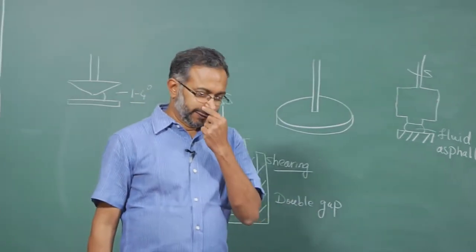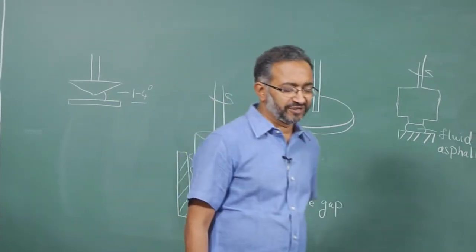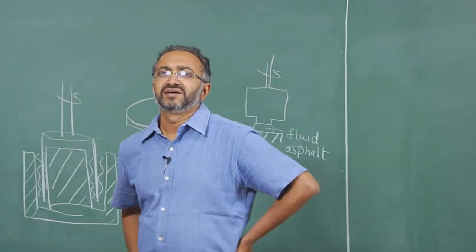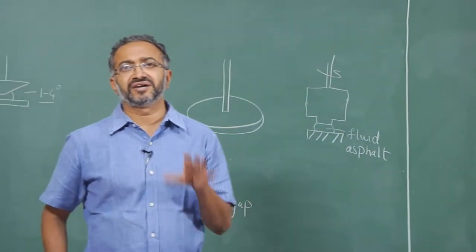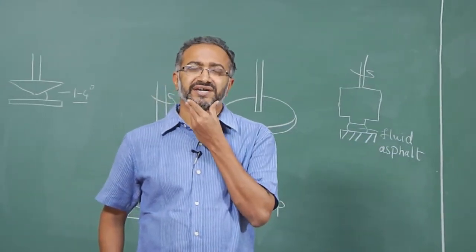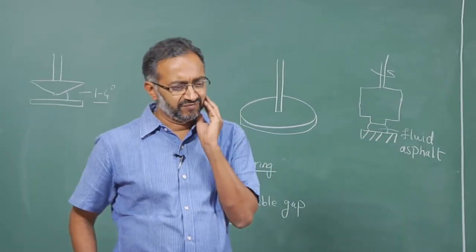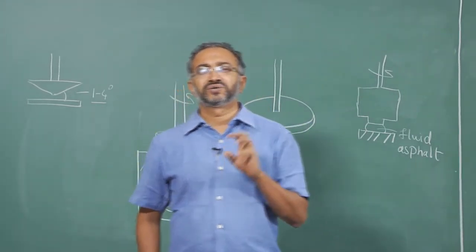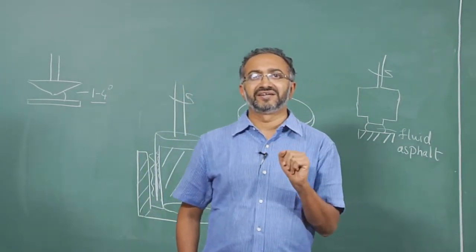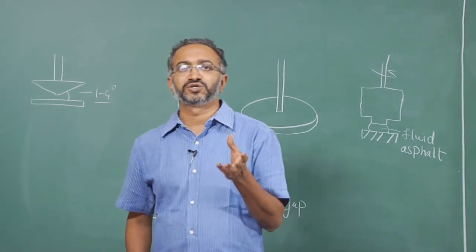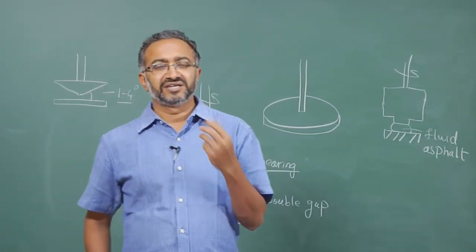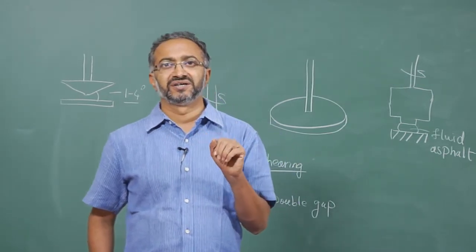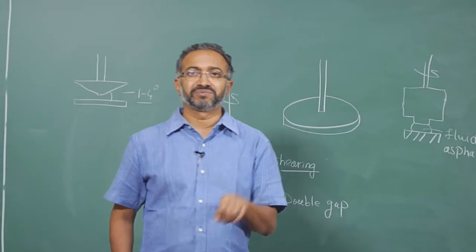So one useful thing in any instrument is to have some standards. Whenever we are trying to measure something, in case of rheology, silicone oils are used as standards. These are available from various vendors, and these are fluids of standard viscosity. So we know what the response of this material is, and to check the working of our instrument, to check the conditions under which we are measuring, it's useful to always use these standard fluids. So first off, I'll show some data.